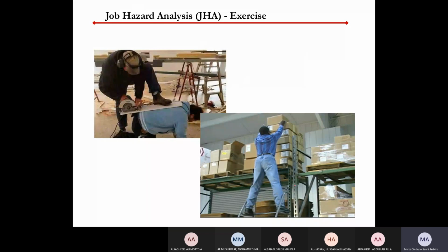You could see the way he's standing. Okay, all right. Because teacher, when I go to the supermarket, for example, I see a lot of workers doing this same unsafe thing. Well, this is wrong. For example, if you want to bring things down, you have to use proper access equipment. And if you must use a ladder, then you must have at least 3 points of contact on the ladder.